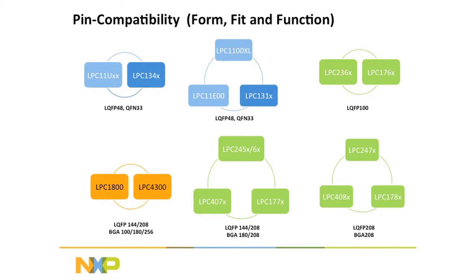And we have similar there as you go around between ARM7s and Cortex M3s, M3s and M4s, even ARM7, M3, M4s in the same pinout. So we have a lot of flexibility. You choose the core that's right for you, and then you can even migrate without changing your board from core to core.